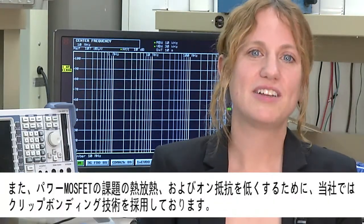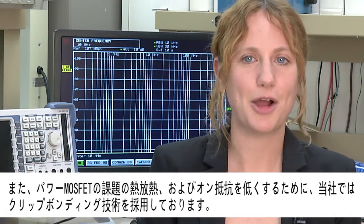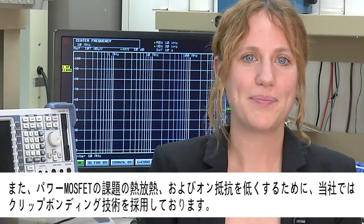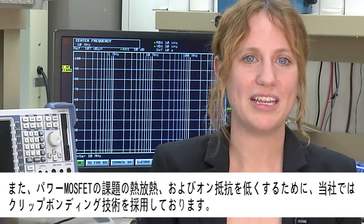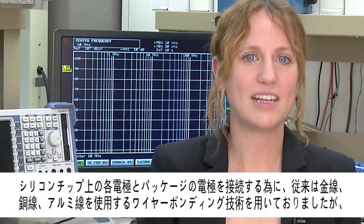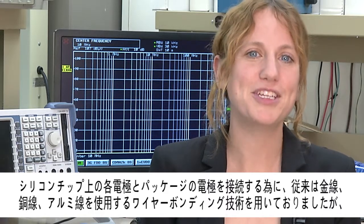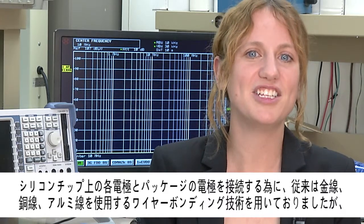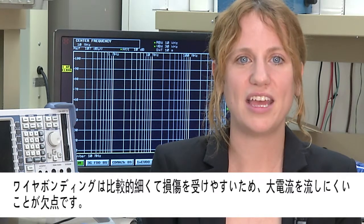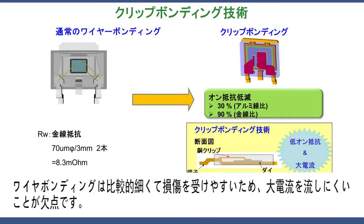We have also adopted clip bonding technology in order to minimize thermal resistance, RTH, to minimize on resistance, RDS on, and to increase current capability, ID max. Formerly, we used wire bonding technology using gold, copper, or aluminum wires in order to connect each electrode on the silicon chip in the package. However, since each wire is relatively thin, it is difficult to allow higher load currents without excess losses.